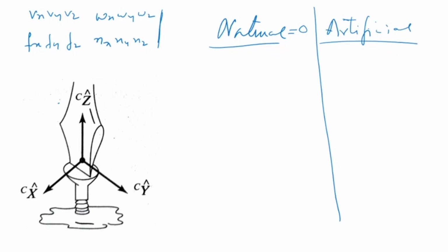So if you look at this task in the x-axis, y-axis, z-axis, can you move in this direction? No, you can't move in this direction. Why? Because the screwdriver is inserted inside the head, so you cannot move in that direction. So automatically the natural constraints are going to become Vx is equal to 0. Similarly, Vz is equal to 0, because you can't have a velocity in the z direction, right? But y direction is free, so you can actually move in that direction. The screwdriver will come off from the head of the screw, but you can still move in that direction, right?